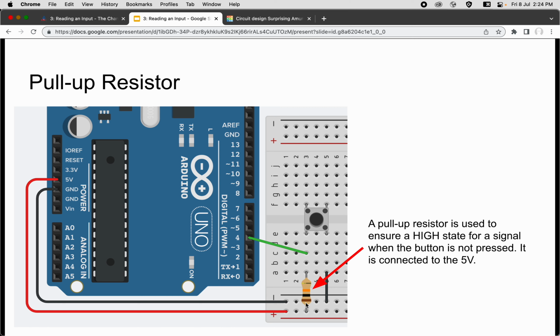So that is the purpose of the pull up resistor. You pull up the value, and when you press it down, it connects this connection. So the power will go from here down and go back to ground. If not, it will just go up here and then go here, so it will read 4 as high. So we are going to do this to show you.